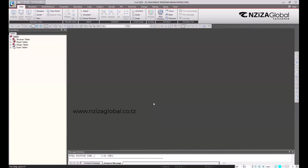So you can see the results for reaction. Okay. You know it is a simply supported beam, right? You see that the reactions are having the same values. And even the live load which is on the beam, it is in the middle, which means that the reactions are sharing the same magnitude of loads.